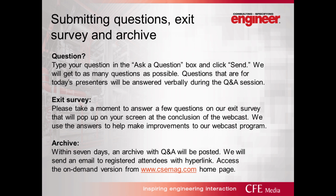Sequencing can be accomplished by either using transfer switches, a time delay, or a building automation system, or a combination of either one. The typical delay of a couple of seconds is enough for the generator to recover and take the next load. So that's what I would recommend.